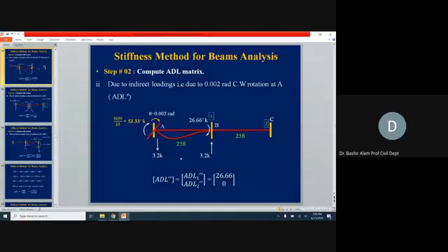Now this we need to balance. Here we have fixed this; we have clamped this C joint, so it is not going to shift this moment to the right hand side. To balance this clockwise moment, which is the summation of 53.33 plus 26.67 divided by this span, which is 25, it is coming 3.2, 3.2, and you can see its sign also. The unbalanced moment was in the clockwise direction, so this should be in the counterclockwise direction. Quickly, if you do it, 53.33 plus 26.66 divided by 25, you should be getting 3.2 and 3.2.